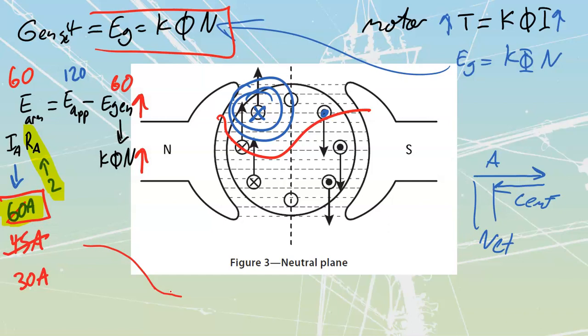We have to be very careful when we start motors up just across the line or applying full values of voltage to them, because if I apply full values of voltage to them, I can get some massive amounts of current that are going to slam in through there. This creates huge magnetic stresses inside of that motor, as well as it's going to cause brownouts in other parts of your system.